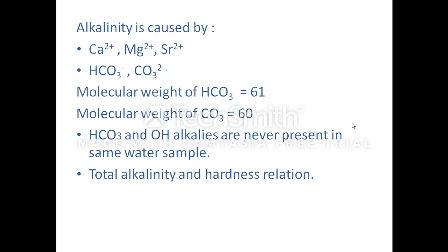The alkalinity is caused by calcium, magnesium and strontium ions, carbonate and bicarbonate ions, and the molecular weight of bicarbonate is 61, molecular weight of carbonate is 60. The carbonate and bicarbonate alkalinity are never present in the same water sample.